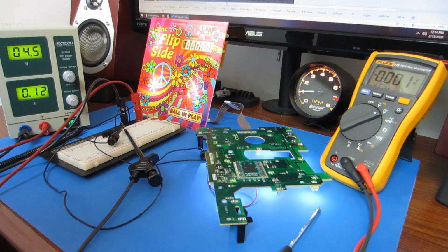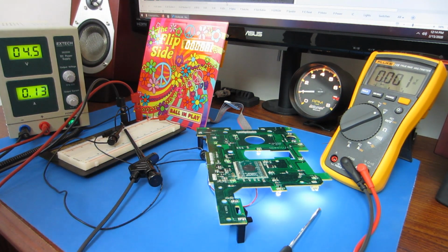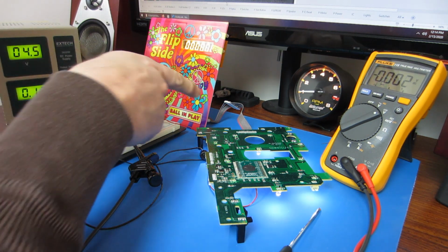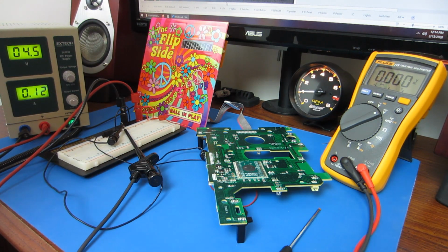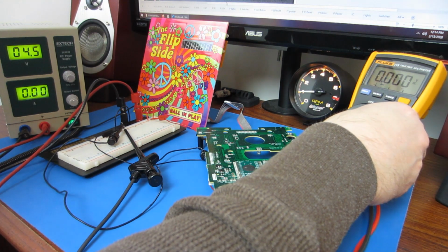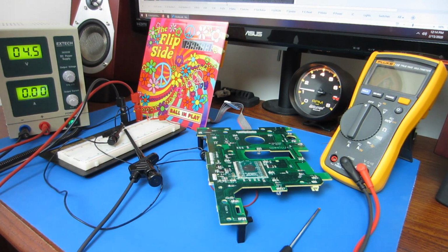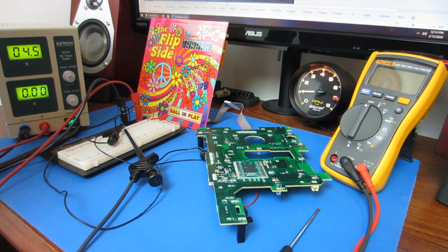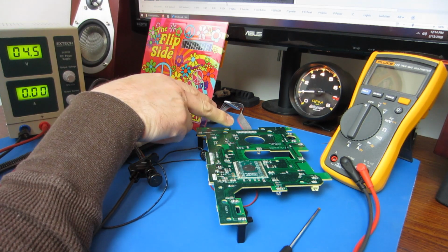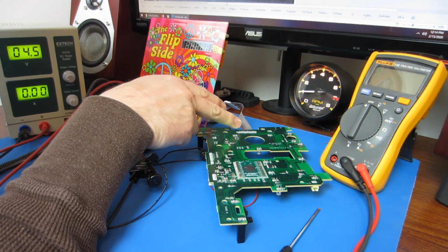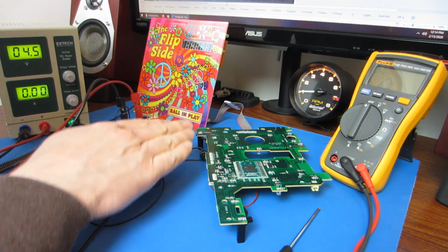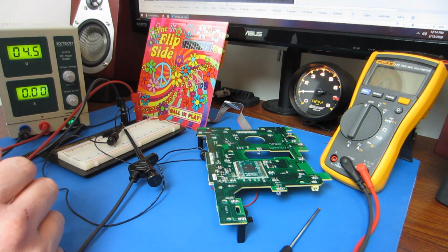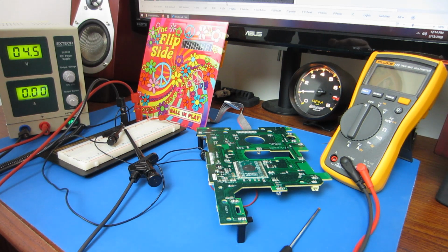Next I want to take a look at the SPI on this ribbon cable here, and to do that I'm going to ditch the multimeter and use a logic probe instead, because if I were to put the multimeter on the MOSI pin, for instance, my theory is that that's oscillating really quickly, so I'll see some voltage on it, but it's going to be hard to tell.